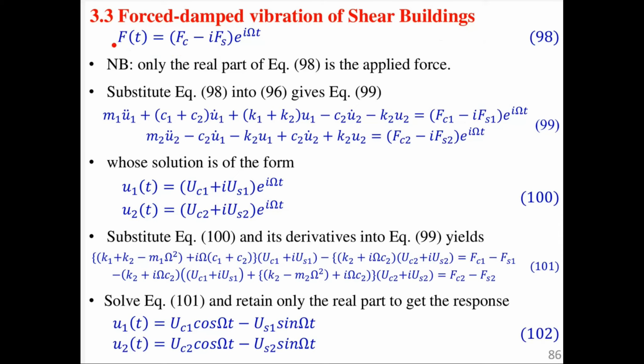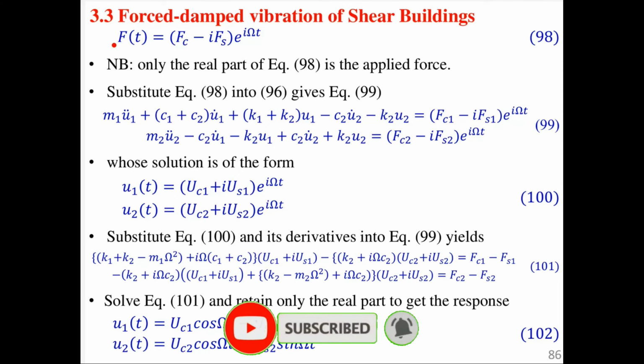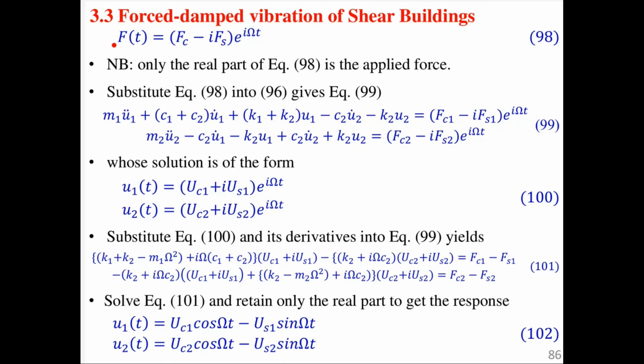Again, remember when we started with damping, and we looked at critically damped, over damped, and then underdamped structure. At an underdamped structure is when we had the vibration. It's when we could say there is a motion that can occur. If the structure is over damped, then it's like immediately the forcing function is applied, the structure comes to rest. The motion decays exponentially. So there's no motion here to analyze, because it means our structure was just displaced and then came back to rest.